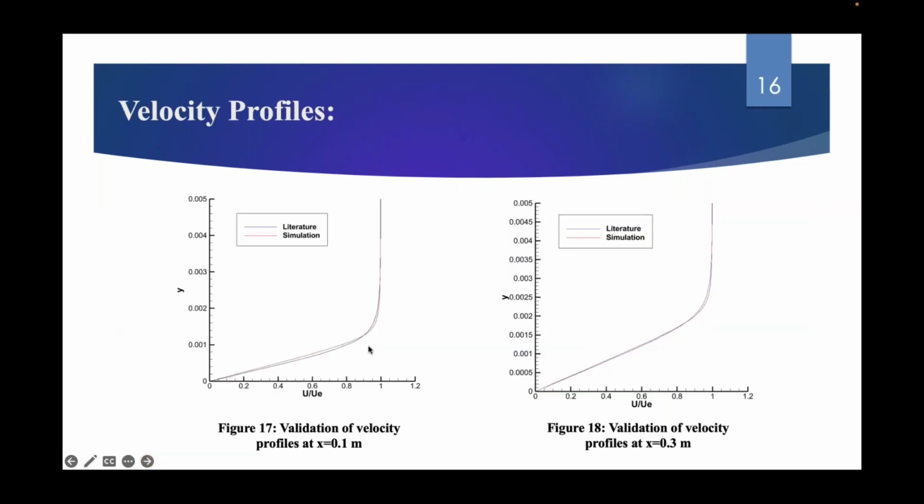So coming to the velocity profiles, the velocities were plotted. You consider a flat plate and you extract the velocity profiles perpendicular to that flat plate. And this is then plotted with respect to the literature value. As you can see, the SU2 simulated data and the literature data are almost coinciding, thus indicating its accuracy.